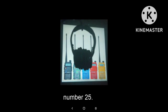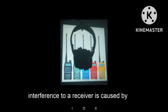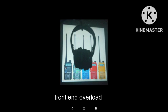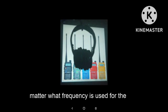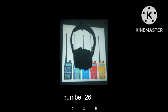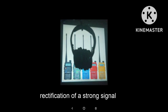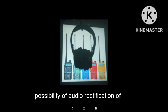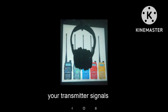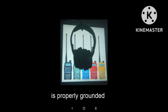Number 25. What is one way to tell radio frequency interference to a receiver is caused by front-end overload? If the interference is about the same no matter what frequency is used for the transmitter. Number 26. Cross-modulation is usually caused by rectification of a strong signal. Number 27. How can you minimize the possibility of audio rectification of your transmitter signals? By ensuring that all station equipment is properly grounded.